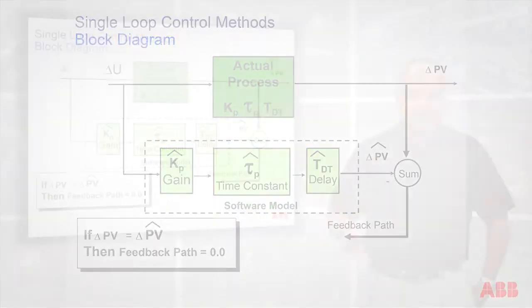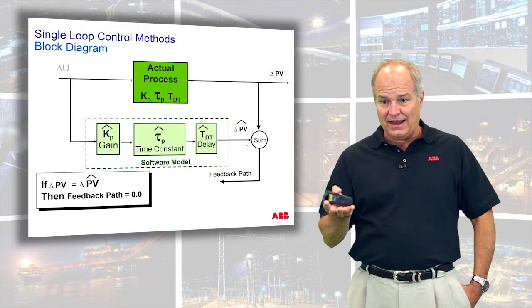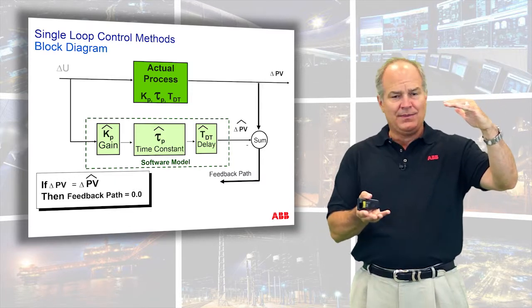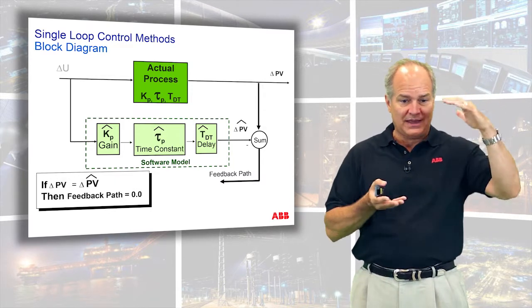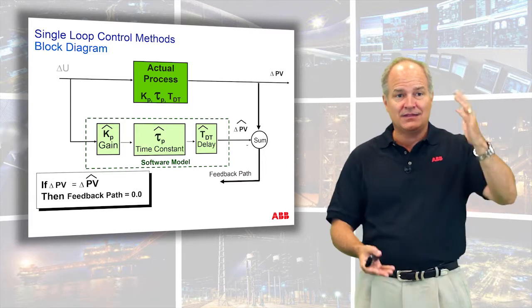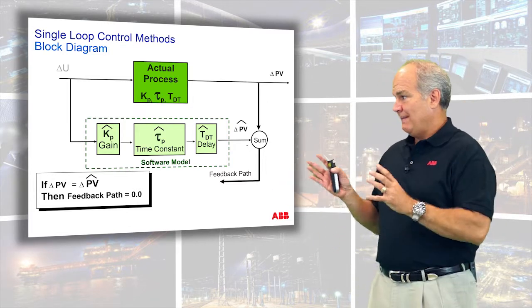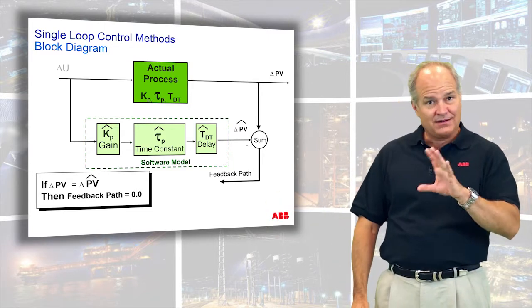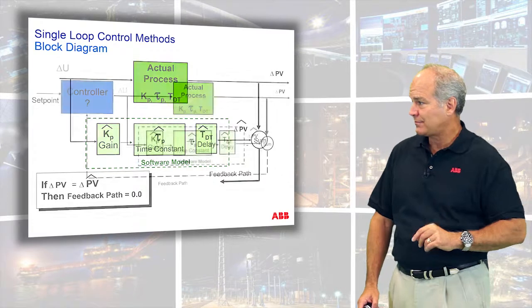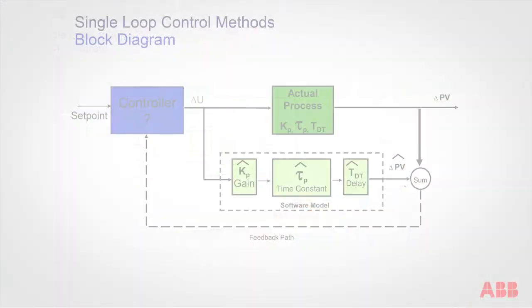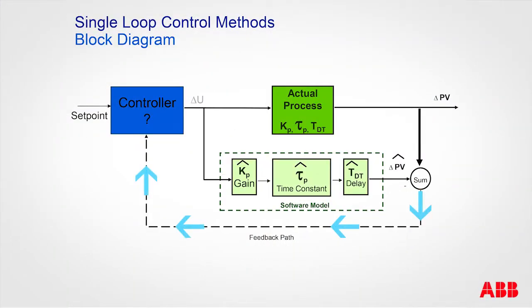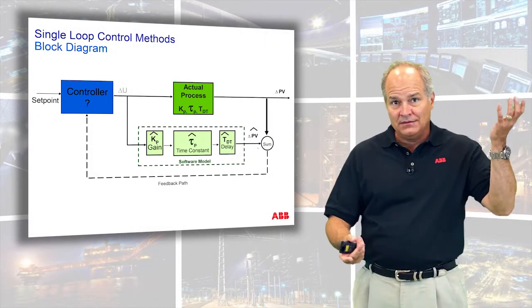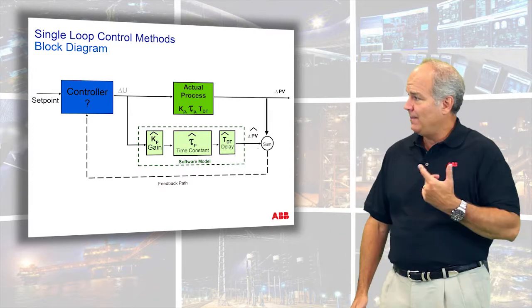They should be 0. So basically, your error path is 0, your set point might be 30 or 50, whatever, and your feedback 0. So in a traditional controller, that difference is the error, and that's why we couldn't use PI or PID with this embodiment. But a lead lag compensator, it doesn't matter, and that's what I want to show you. So here we said, let's just take this and run it into our controller. But we can't use a PI, because the feedback path is literally 0. So how's this going to work? Well, that's what I'll show you.